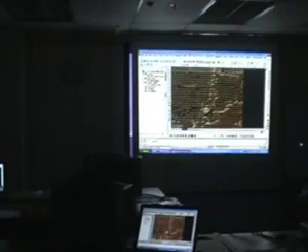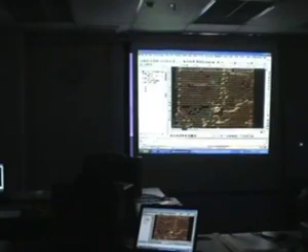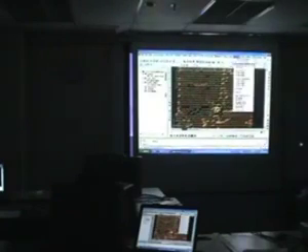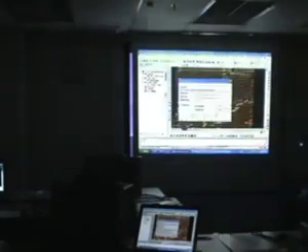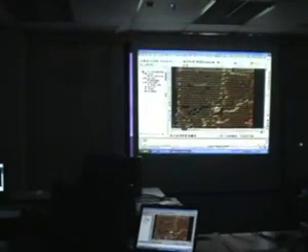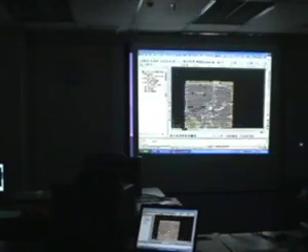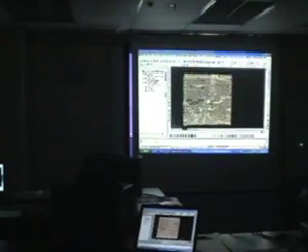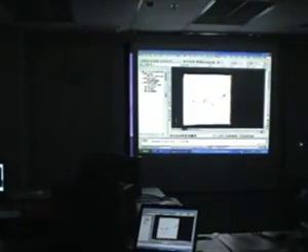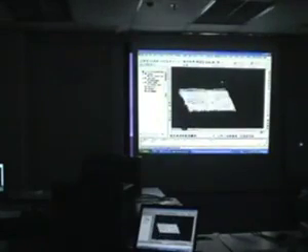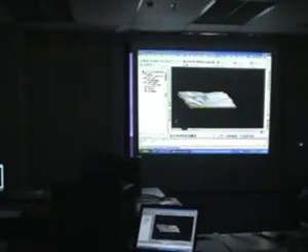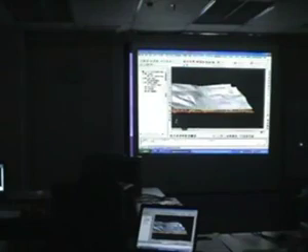Now let's say we want something a little bit more permanent. We want to have the triangles stay there and we view them in 3D as well. We can use 3D faces. So I'm going to click OK. So now even if I redraw, it's still there. I'm just going to show you what it looks like in 3D. Say I give a shade here so it's a little bit clearer. You can really see the lighting, how the light falls, how the light shadows. I'm just going to put this in 3D so you can see. Okay, this is what the surface looks like.